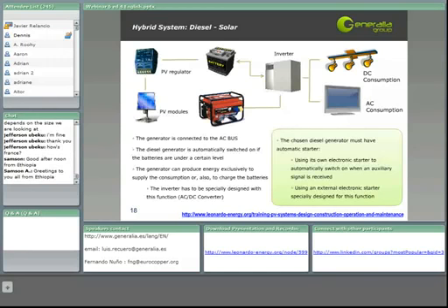You can check that the diesel generator is connected directly to the inverter with the alternating current bus, and how it works is that if the batteries get to a certain level of discharge, the inverter detects this level and sends a signal to the diesel generator so that it will start working and producing energy.